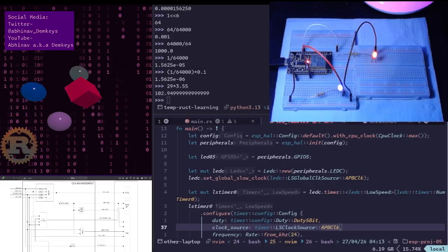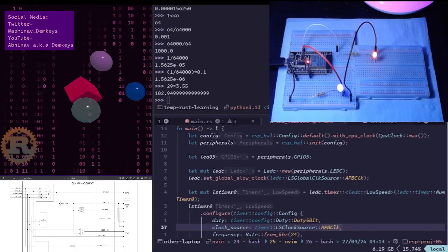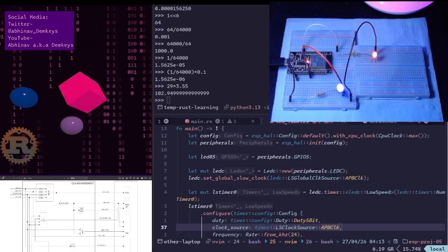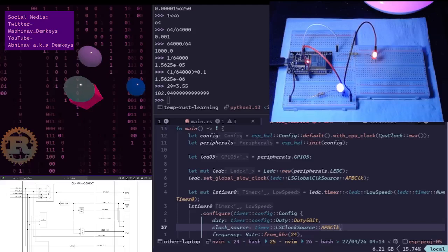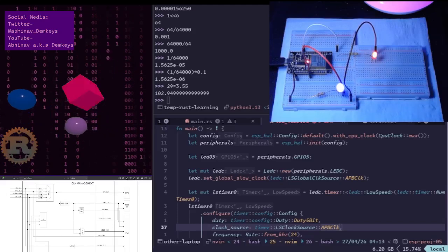So it mentioned this: to answer your specific question, the standard route for high performance operation is XTAL to PLL to CPU clock to APB clock. Here's how the signal flows and divides. From the XTAL, it's a 40 megahertz signal. This is your base reference.